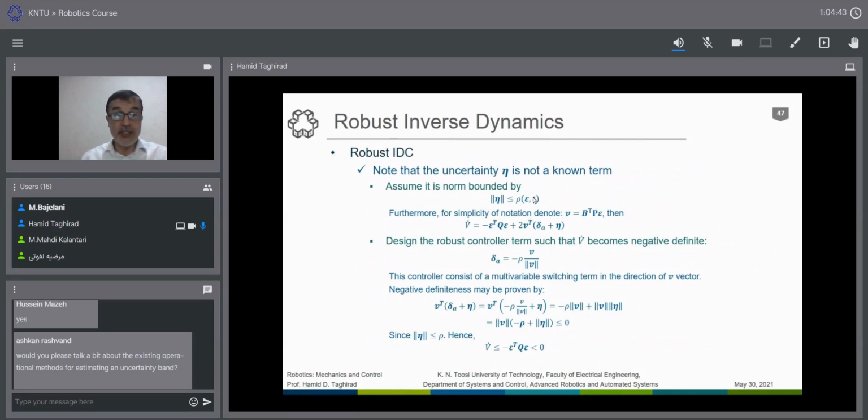The gravity term can be measured statistically, but the other one, the Christoffel term, should be considered just by a dynamic experiment. You have a dynamic model of the system. You have something that you can measure, the torque, or the current in the motor machine, and you find the difference between these two, all together, as the uncertainty term. If you can measure exactly what it is, then you have the eta quite well.